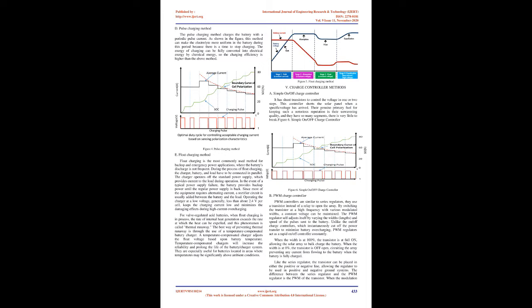C. Lithium-ion, Li-ion. Lithium-ion, Li-ion, is the new standard for portable power. Li-ion batteries produce the same energy as NiMH but weigh approximately 20–35% less. They do not suffer significantly from the memory effect, unlike their NiMH and NiCd counterparts. Their substances are non-hazardous. Because lithium ignites very easily, they require special handling. Unfortunately, few consumer recycling programs currently exist for Li-ion batteries at this point.